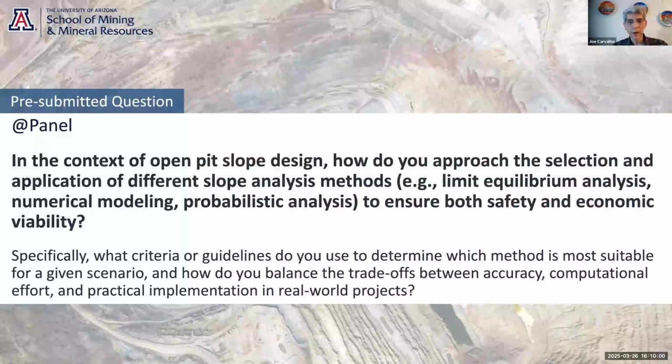Okay, that's a mouthful. So yes, I've always believed that you walk before you run. So I think you start simple. It really depends a lot on the available data. No point in going into a very complex model without the proper data to feed the model. I would say you'd start with a limit equilibrium analysis, as was said here today. They have advanced to the point where you can actually include quite a bit of anisotropy and other niceties that we didn't used to have in the early days.